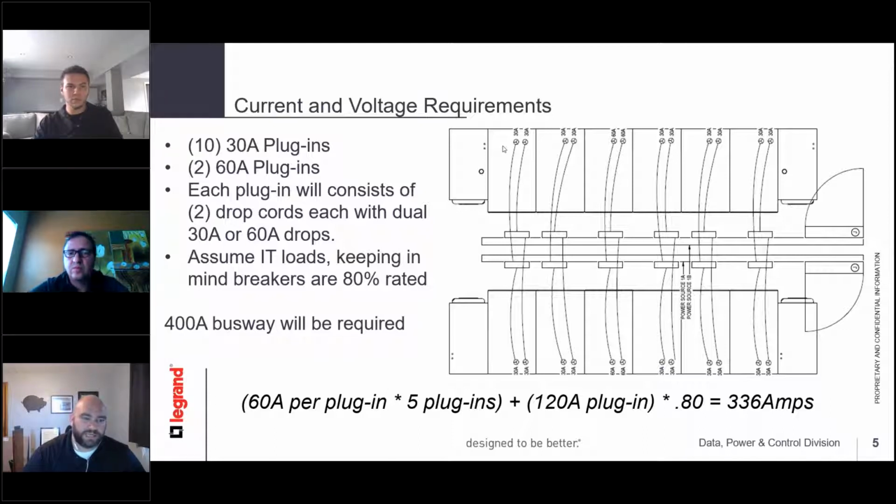Yeah, Nick, and to add to that, for those situations where, based on the upstream amperage, you have a high incident energy count, we do have a rotating paddle type plug that we can go into. We plan to go into it in a later session. It's specifically designed to remove the operator from the approach boundaries when actuating the paddle into the busway. Absolutely. So we have options based on your specific application and situation to meet whatever needs you require. Perfect.